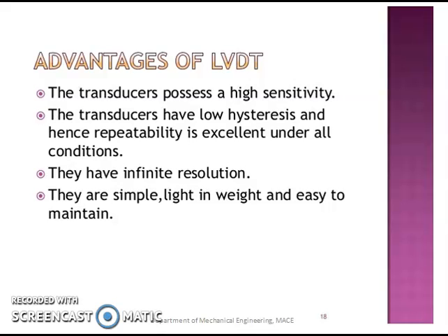This LVDT has very good advantages, like it possesses very high sensitivity, and these transducers have low hysteresis, and repeatability is excellent under all conditions. Another advantage is it has infinite resolution, and an advantage that makes the LVDT very common is it is very simple, light in weight, and easy to maintain.